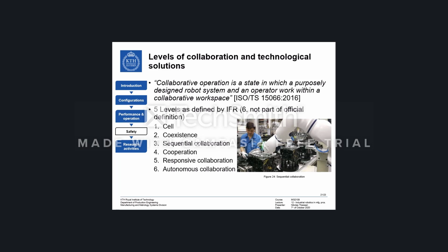Audible and visible warning systems are not acceptable for safeguarding methods, but they may be used to enhance the effectiveness of positive safeguards, such as the presence sensing devices. The presence sensing detectors that are most commonly used in robotic safety are pressure mats and light curtains. Floor mats, pressure sensitive mats, light curtains similar to arrays of photocells, and laser scanners can be used to detect a person stepping into a hazardous area near a robot.